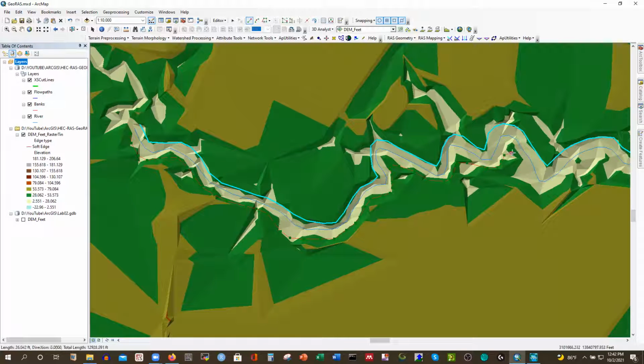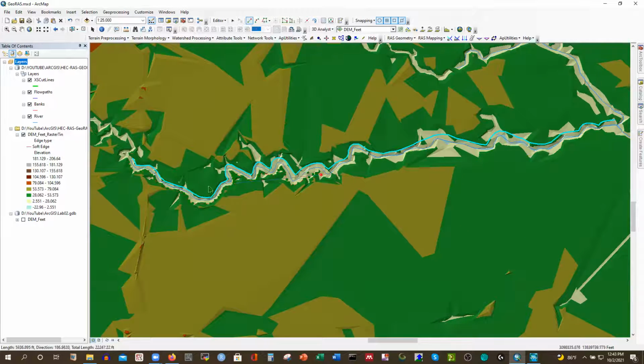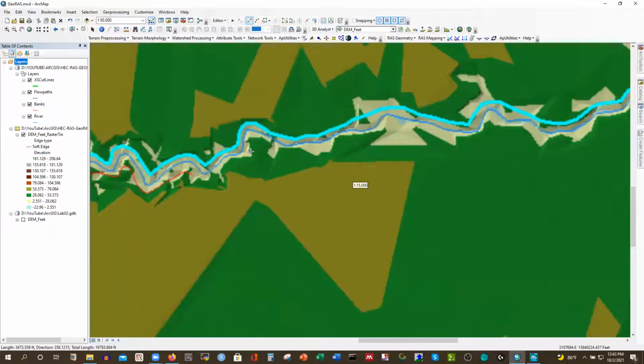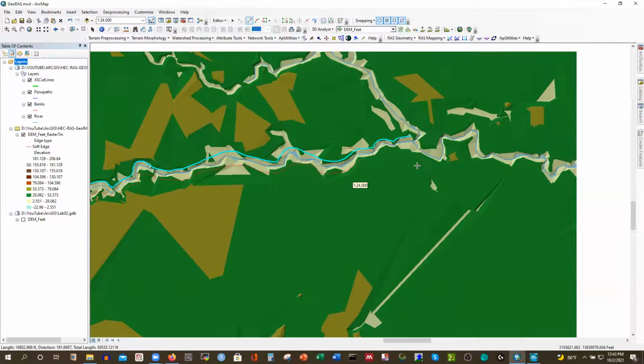Here it is. If you have high resolution data, like the LiDAR data that I was talking about, you can find 1 meter resolution for some parts of the US, and then you can use that. I already used that in my other model, the Delta model for flood modeling, which needs very high resolution data to resolve small streams. But for the HEC-RAS model, if you just want to run the model for bridge scouring or any other thing, you don't need that high resolution data. But if you have it, then it's good.